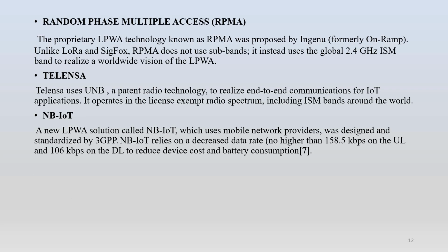The last part is random phase multiple access. The proprietary LPWAN technology, known as RPMA, was proposed by Ingenu, formerly known as On-Ramp. Unlike LoRa and Sigfox, RPMA does not use subbands. It instead uses the global 2.4 GHz ISM band to realize a worldwide vision of the LPWAN.